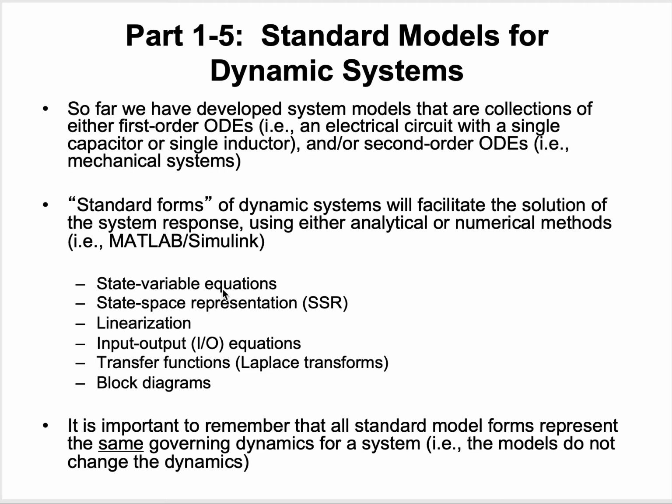State variable equations were the generic system dynamics equation for a general system, both linear and nonlinear. And state space was the representation for only linear systems. And if the system is nonlinear and we would like to linearize it for some reason, then we also discussed linearization for that.